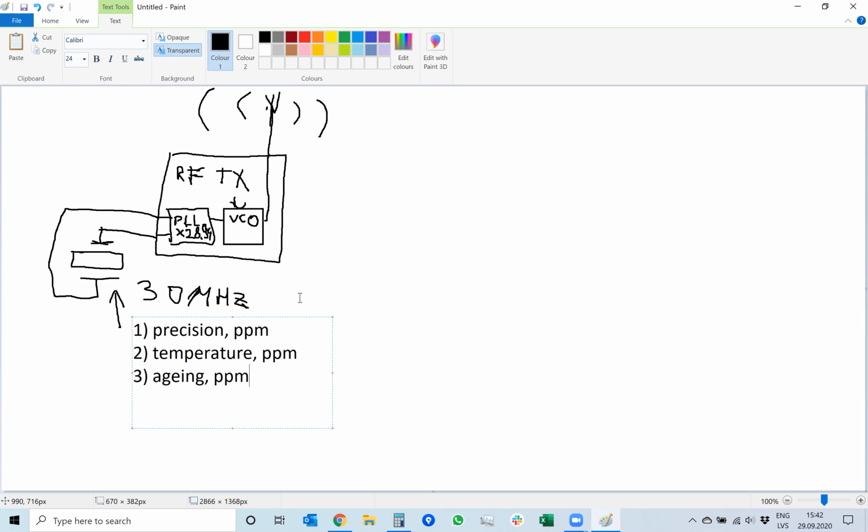It is measured that after something like 2 or 3 years, the crystal has changed its frequency by several ppm because of aging. After that time, the stress has stopped, or the stress has reached its equilibrium.